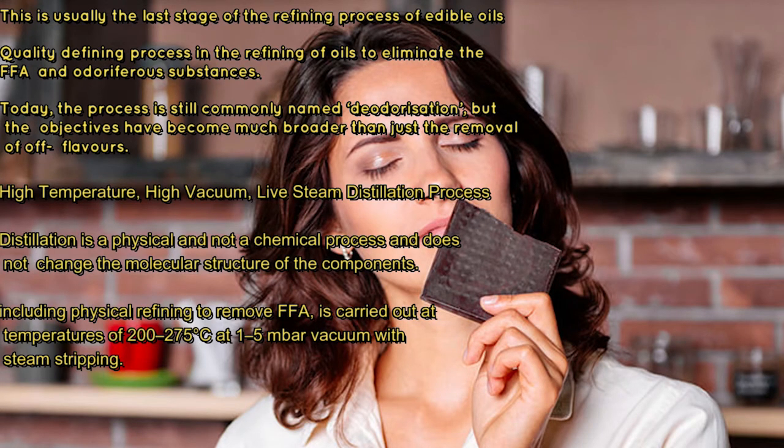Quick info: distillation is a physical and not a chemical process and does not change the molecular structure of the components, which includes physical refining to remove FFA. It is carried out at temperatures ranging from 200 to 275 degrees Celsius at 1 to 5 millibar vacuum with steam stripping.